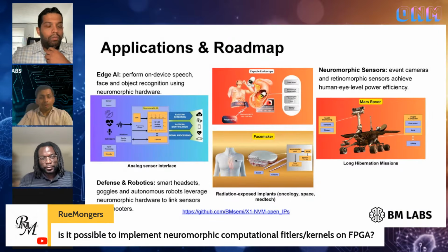Yes. So what you can do is take our behavior model and implement that Verilog on an FPGA. The behavior model is Python-based. You convert it into Verilog. That Verilog can be synthesized by OpenLane for chip manufacturing, or you can use an FPGA, a Xilinx synthesizer, things like that, and implement it on FPGA.